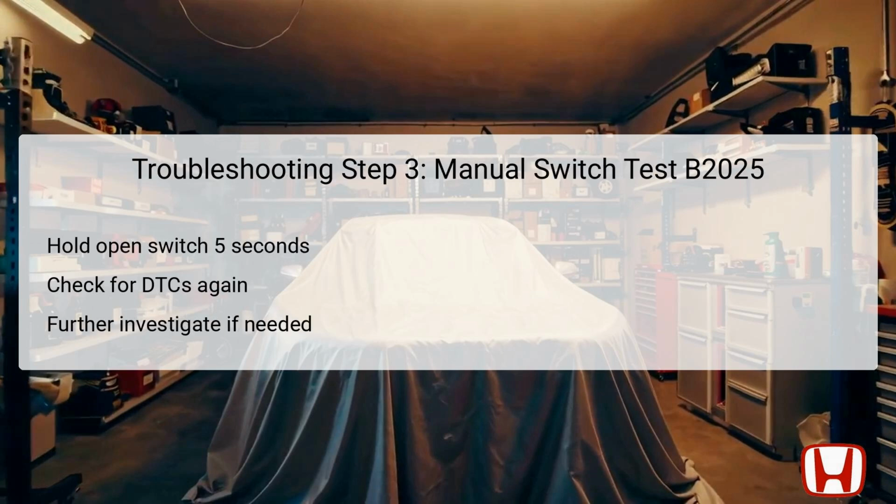In this step, you'll need to press and hold the open side of the left power sliding door switch for a minimum of 5 seconds. This manual activation helps test the switch's functionality and its response being sent to the control unit.